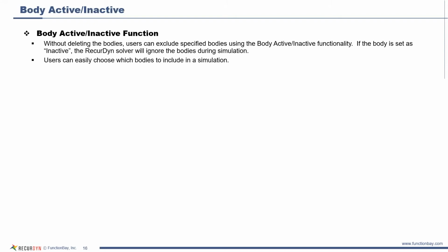So before, users were able to deactivate forces and joints, but now you can also apply this to bodies. And when you do this, that particular body will be ignored by the solver during the simulation. And it will also be grayed out in the modeling window.